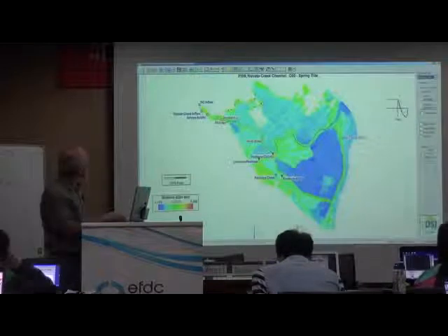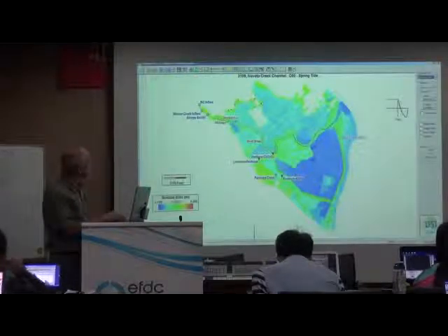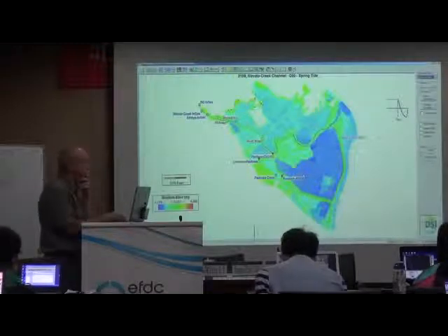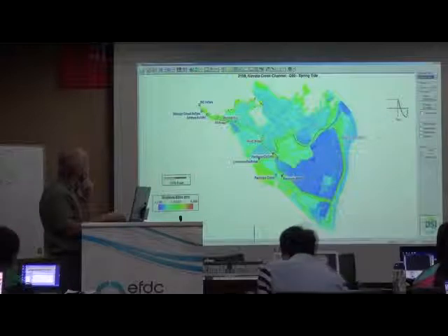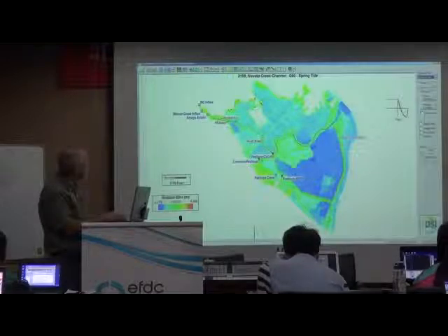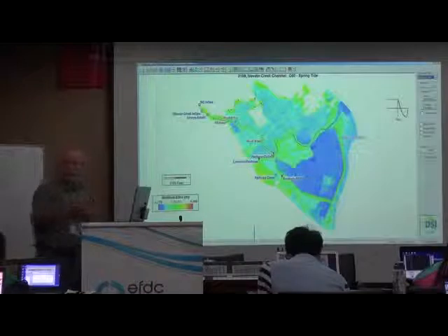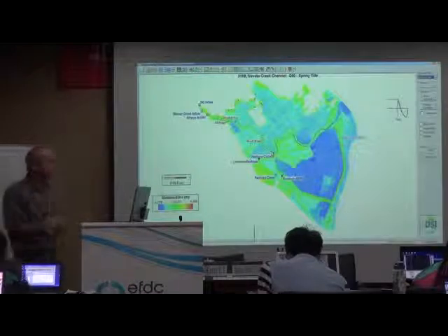So we have a diked system through here in large areas of lowland agricultural land, and there's all these hydraulic structures controlling flow between some of these different diked areas, and then outlets from a diked area into the river. And these are all hydraulic structures with rating curves that are downstream dependent flow conditions.